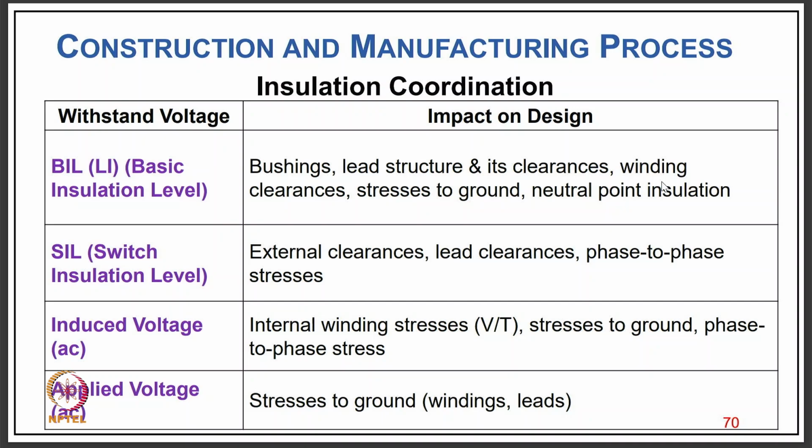So this is related to insulation coordination, with the withstand voltage we call BIL, basic insulation level. And of course the impact on design is about the bushing, lead structure and its clearances, winding clearances, stresses, and ground neutral point insulation.